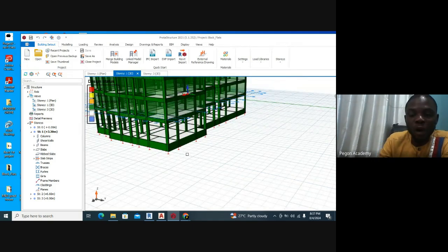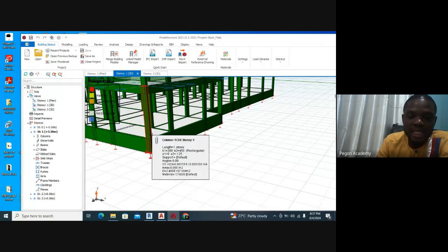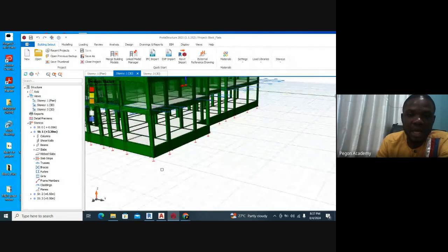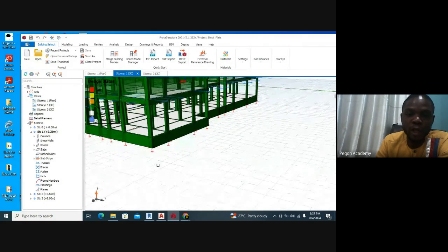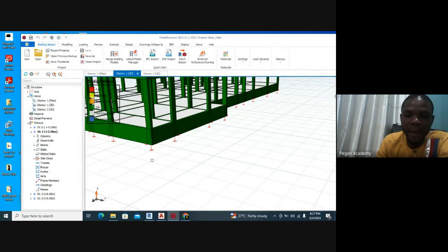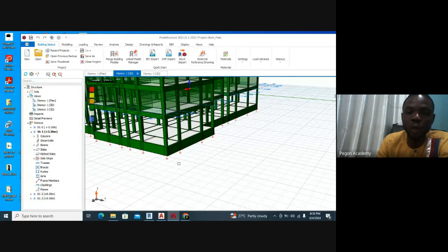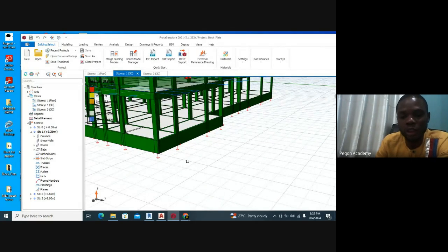Now, because the soil is stable, it is not going to affect the structure, because all the loads come individually on the pads, and the soil is stable, so it takes them individually. Now, for the sake of a raft, where the soil is not okay or the soil is not so strong, the soil bearing capacity is not high.